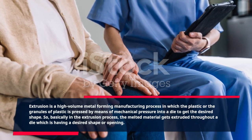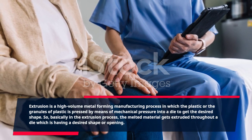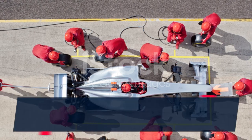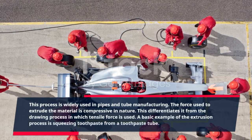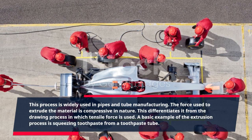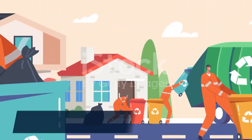Basically, in the extrusion process, the melted material gets extruded through a die which has a desired shape or opening. This process is widely used in pipe and tube manufacturing. The force used to extrude the material is compressive in nature. This differentiates it from the drawing process, in which tensile force is used. A basic example of the extrusion process is squeezing toothpaste from a toothpaste tube.